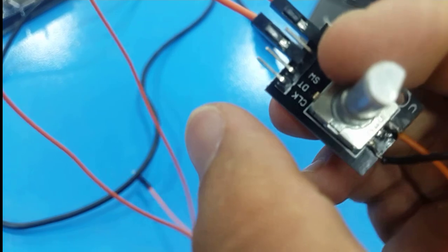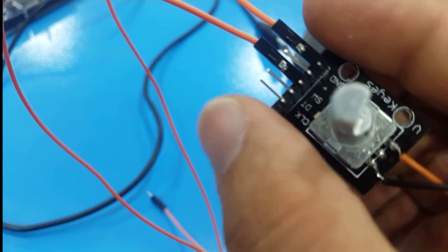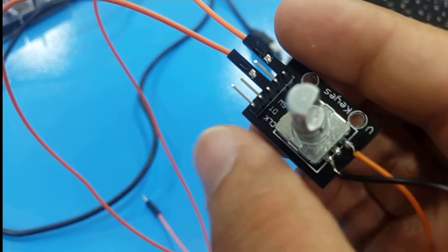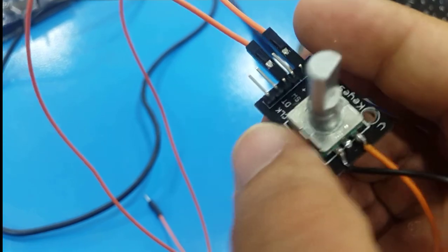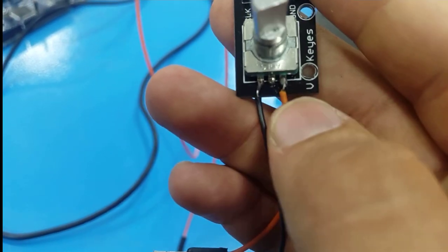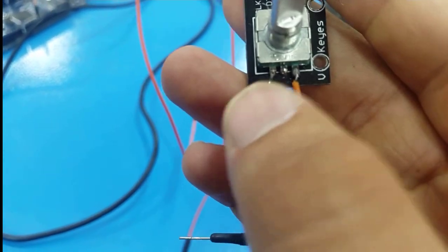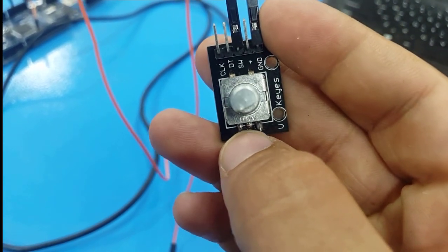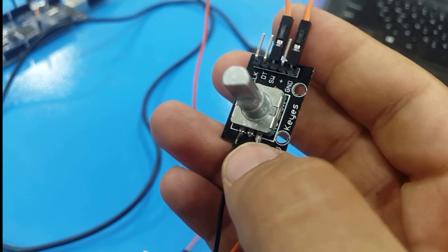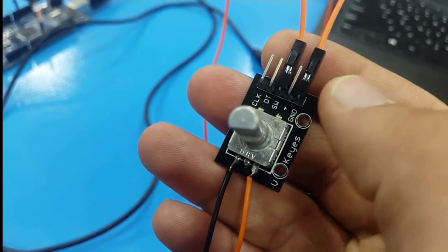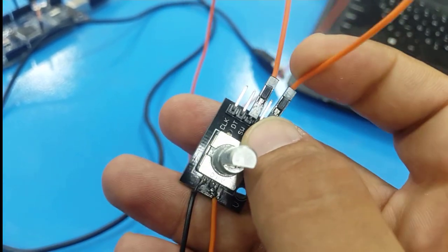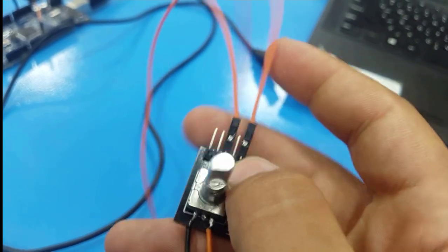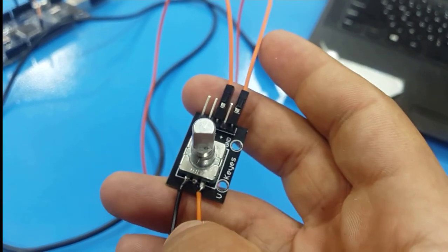And also, you see, I didn't use the data and clock pins, which will usually be used with this board. I didn't use these 2 pins. Instead, I connected these 2 wires to the pin A and pin B of the rotary encoder. You don't need to connect the middle one, which is the ground, because this ground is already connected to this ground pin. So I use this ground pin header board for grounding all the boards.